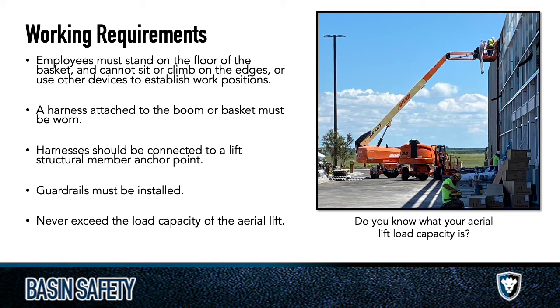Guardrails must be installed and never exceed the load capacity of the aerial lift. This can be tough. Most lifts are designed to carry 2 people, but some of them are only designed to carry like 300 pounds. I know a couple around here that are 350 pound lifts. There are no 2 people standing around here that can both get on that lift right now. We don't have 250 pound guys just around, so it's essentially a 1-person lift.